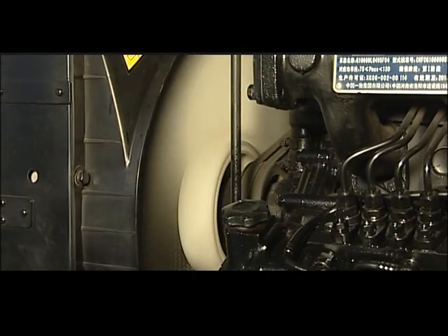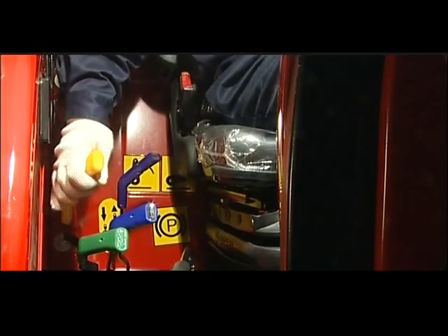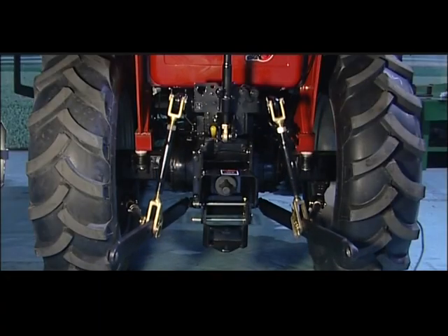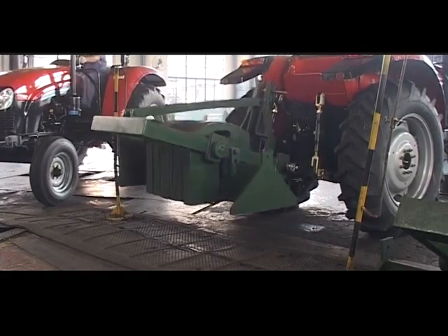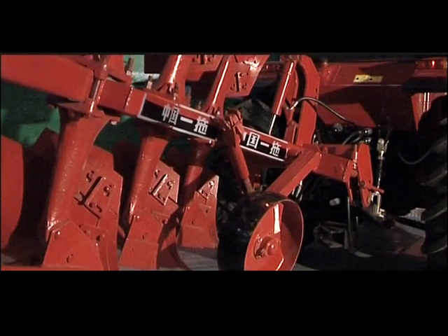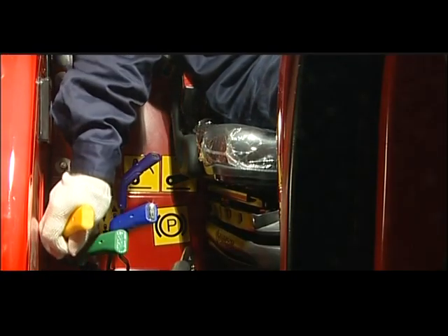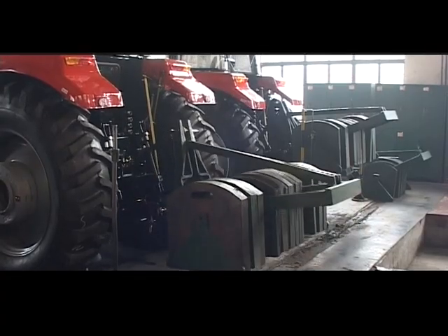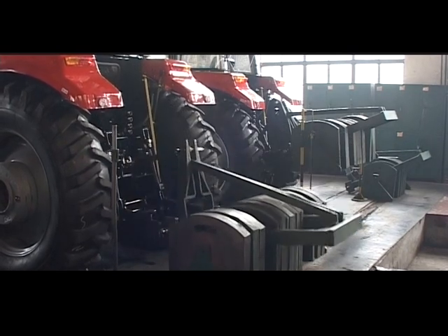Hydraulic system running in. After starting up the engine, locate the throttle at mid-position to run the engine. Operate the position control lever and observe if the hydraulic system works freely or not. Hang on heavy objects about 0.6 tons or implement with equivalent mass on the hitch device. Run the engine at big throttle. Operate the position control lever. Let the hitch device freely go up or down at full stroke.